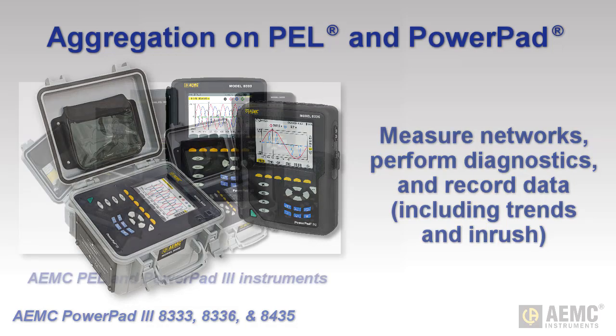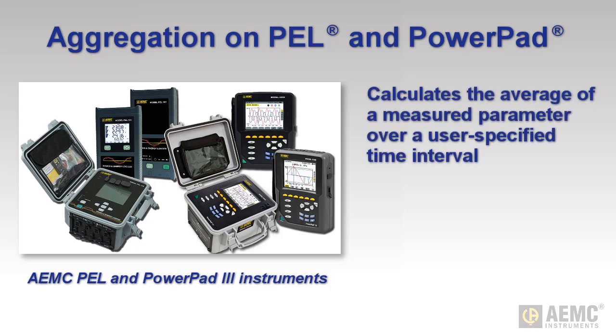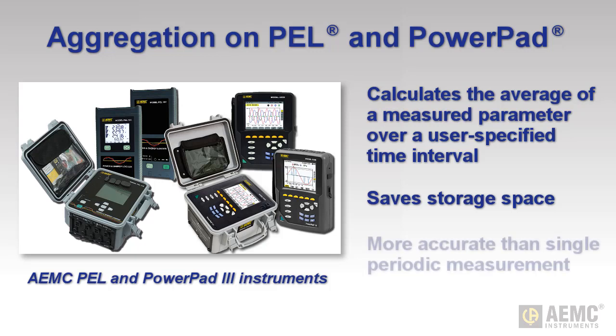When recording data, AEMC PowerPad and PEL instruments perform measurement aggregation. This involves calculating the average value of a measured parameter over a user-specified time interval. Aggregation saves storage space by reducing the number of measurements recorded over the duration of the recording. It also ensures accurate data by including all individual measurements in the aggregation rather than periodically taking a single measurement.